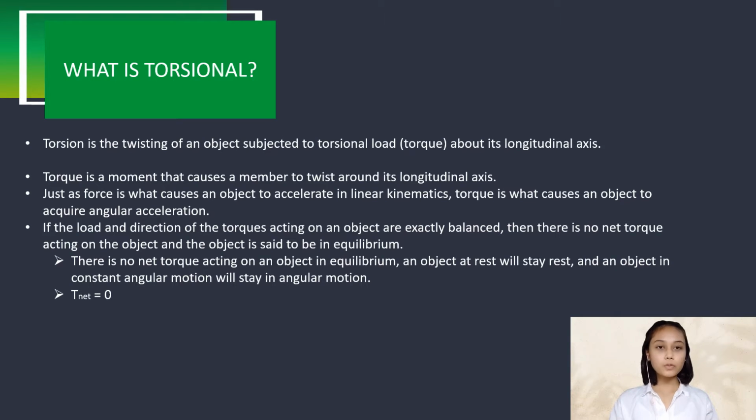To visualize what I'm talking about, imagine that this is a rod, and the cross-section of the rod is a clock with just an hour hand. When no torque is applied, the hour hand sits at 12 o'clock. As torque is applied to the rod, it will twist, and the hour hand will rotate clockwise to a new position. Let's say it is 2 o'clock. The angle between 2 o'clock and 12 o'clock is referred to as the angle of twist, and is commonly denoted by a Greek symbol. This angle lets us determine the shear strain at any point along the cross-section.